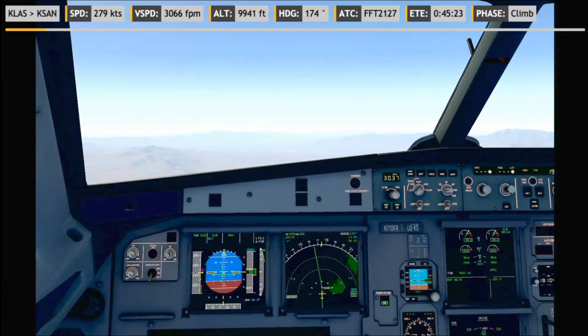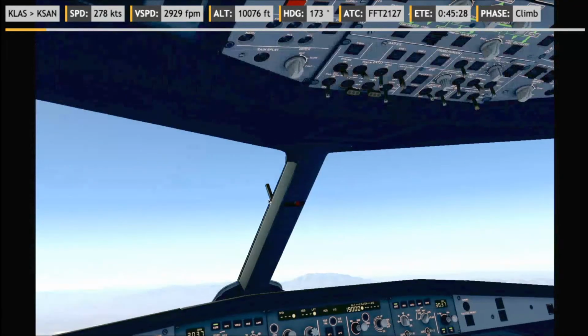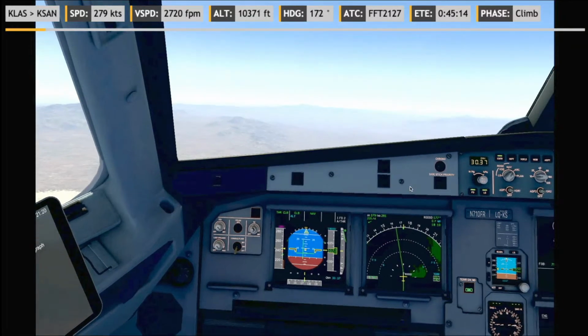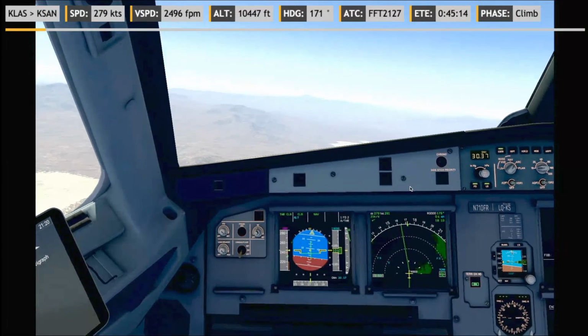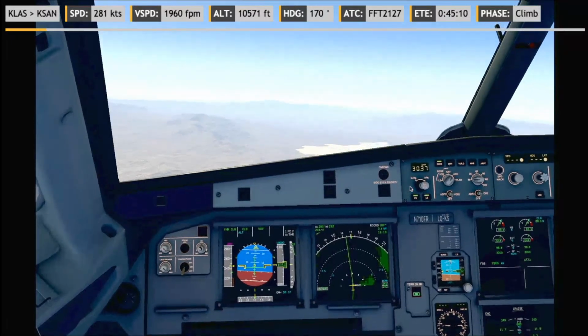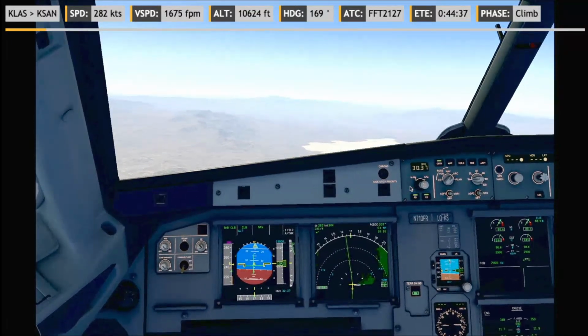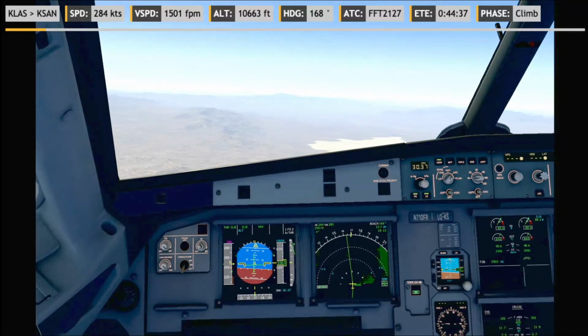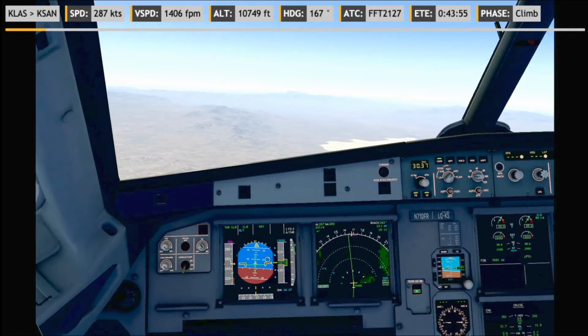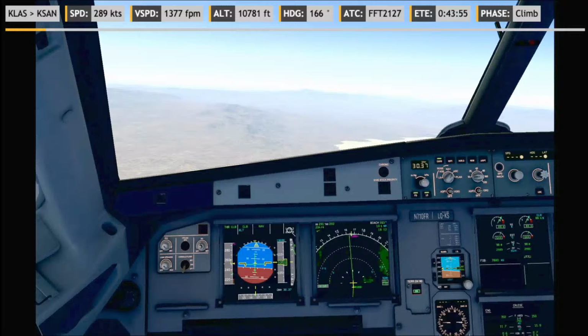Approaching 10,000 feet. Alright, there we'll go landing lights off. And seatbelt sign can come off. It's really smooth air, so we don't need our passengers in their seats. As long as I can fly it smoothly, it's fine. I like flying it manually, so I'm gonna do that. Above 10,000 feet, our speed restriction is dropped, and our airplane starts to accelerate, therefore reducing our rate of climb a little bit.